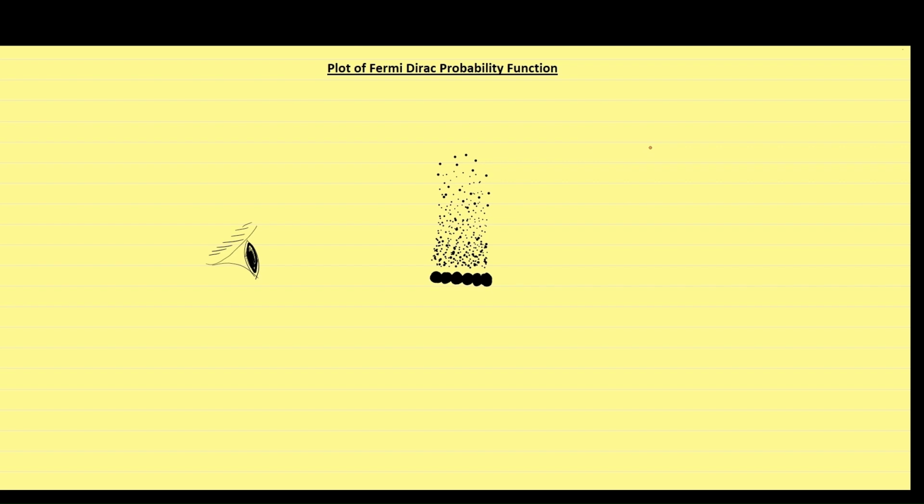You would not be able to see any line there, neither the conduction band minima energy level EC, nor the maxima energy level of valence band EV, nor the Fermi energy level EF. These lines are reference energy levels, which we use to make our understanding easier. Likewise, we have assumed that EC is the minimum energy of electrons which can be considered to be present in conduction band, increasing the conductivity of the semiconductor.